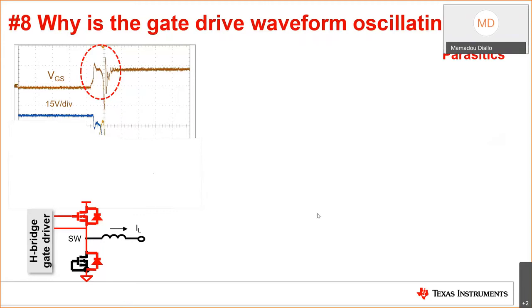Okay, let's see. Looks like the majority of the answers picked option C, which is the closest answer here, and I'll widen this up here. Option C, large inrush current due to the long reverse recovery times of the MOSFET body diode. That's absolutely correct. Also high dI/dt as well. So the better option here is B and C combined, which for this case is essentially showing how very high dI/dt can couple back to the gate of the transistors.